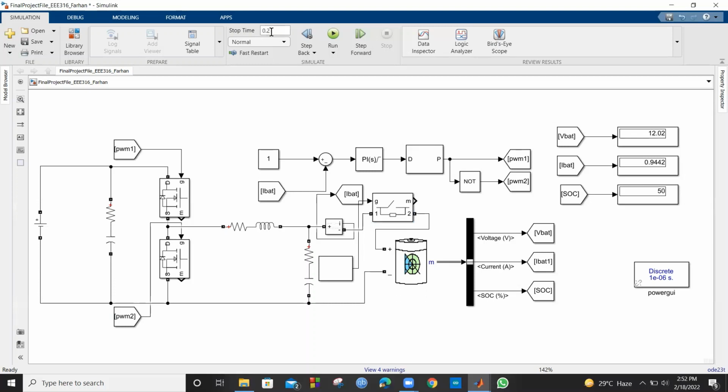For this, we will now see the project simulation, and for the entire part, we will see for the 0.75 seconds, we have given a state generator signal for which the total 0.75 seconds have been divided into two parts. For the first 0.5 seconds, the battery will get itself charged, and for the later 0.25 seconds, the battery will have its internal discharge current having a nominal voltage drop in it to result in the final 12 volt after